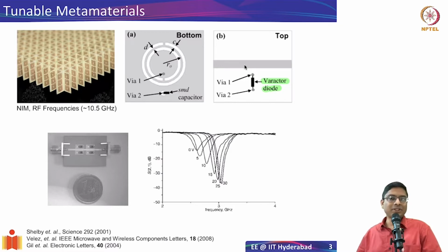Well, there is this depletion region that is formed, right? And as you apply a reverse bias voltage and change it, the extent of the depletion region changes, and the space charge region changes. So essentially this device, a semiconductor diode in reverse bias, operates like a capacitor. And the capacitance is simply the epsilon of the material divided by the width of the depletion region. You would have studied that in semiconductor courses.